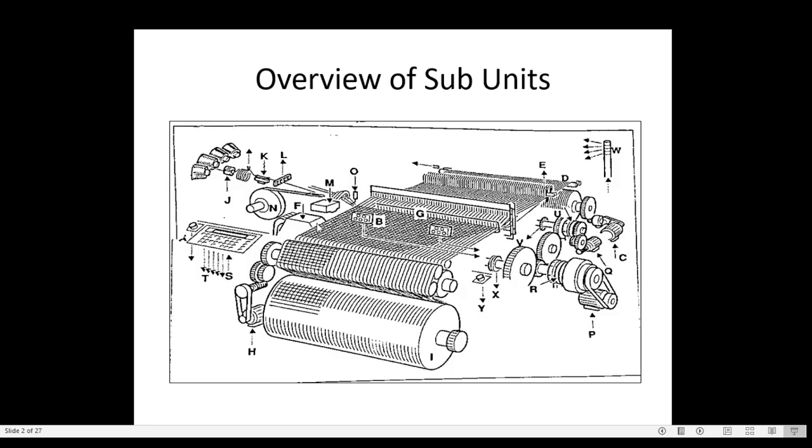From left side of machine it goes to the dobby, here the dobby is there, or jacquard is there, F is shown in the figure. Again from this the drive goes to the weft selector device. So we can see here M is the weft selector, 1 2 3 4 5 colors are there, so 5 wefts will be there.